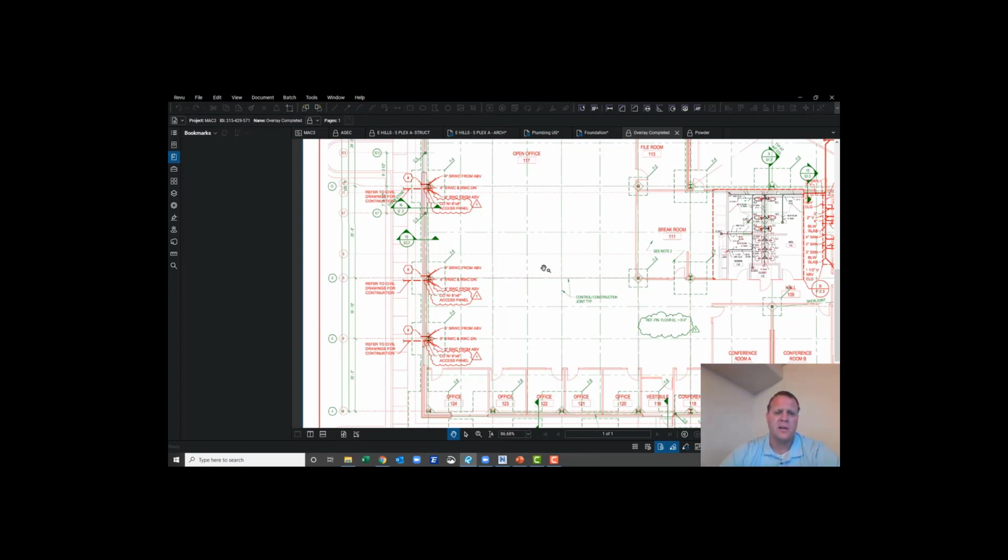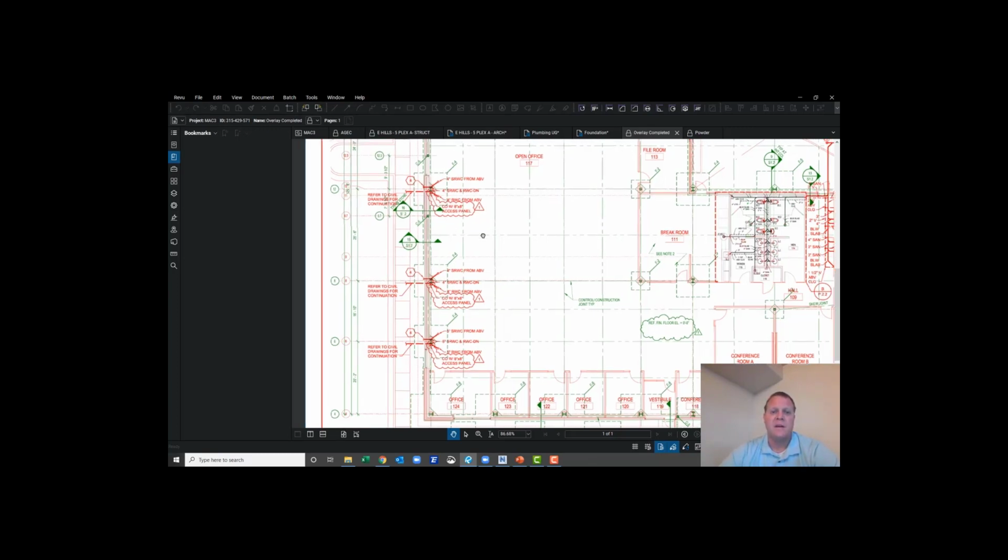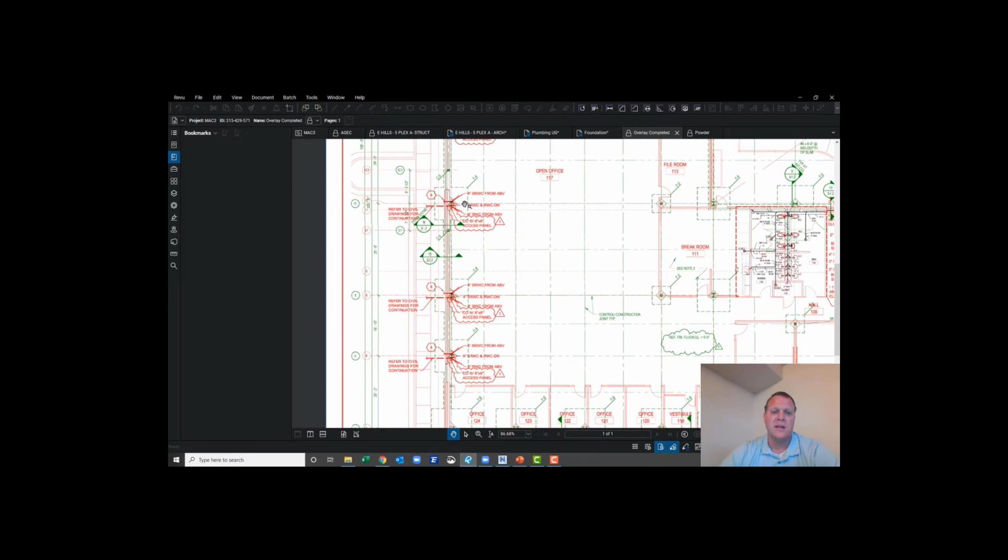And a good general contractor, a good site supervisor should be able to see pretty quickly, okay, we've got pipe, foundation. Let's just see what's there. And flipping through a few drawings, you should be able to find this pretty quick. And there's a coordination issue. So what happens if we don't coordinate this stuff? What if we don't think through the construction sequence?